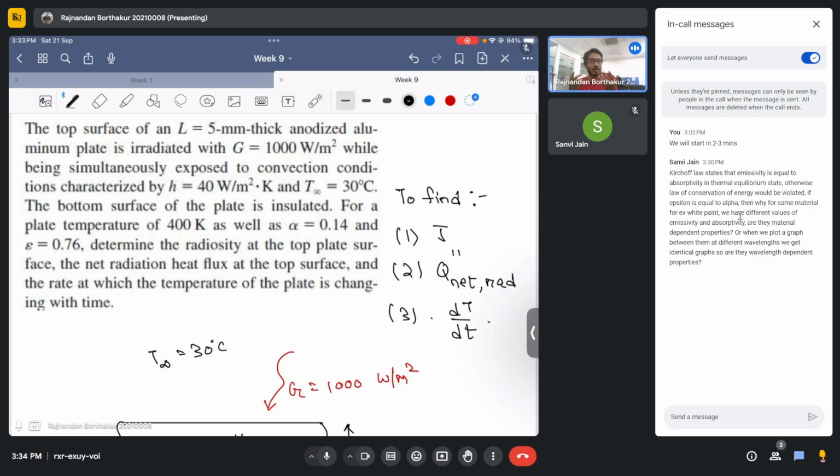That is because these sorts of materials have spectral dependence, and when they do, the net radiation heat transfer depends on the wavelength at which it occurs. That's why they are known as spectral properties. So for the same material, radiation heat transfer can be different based on the wavelength you are operating on. Similarly, you can show that it is also dependent on direction.